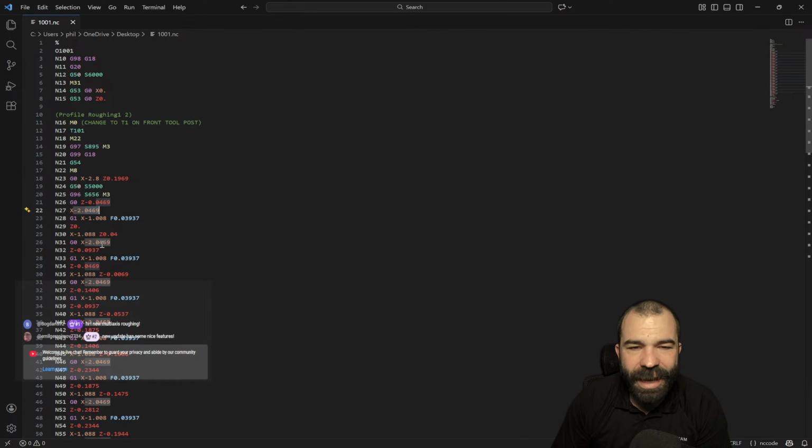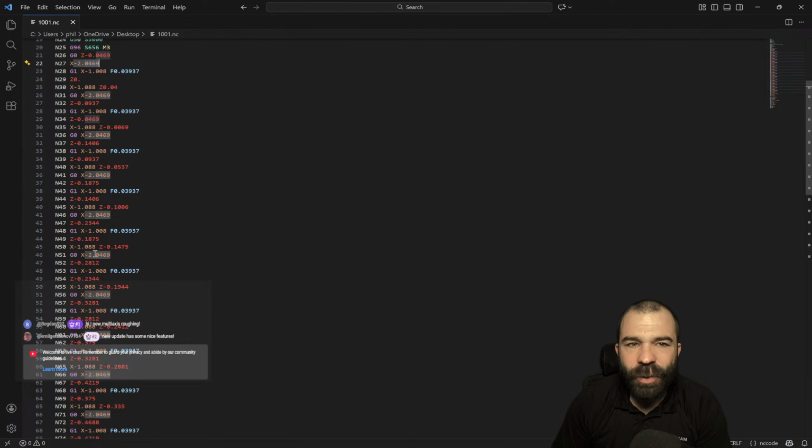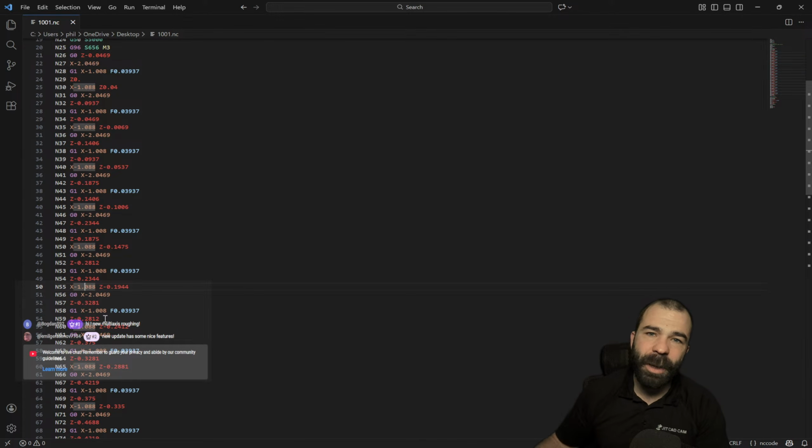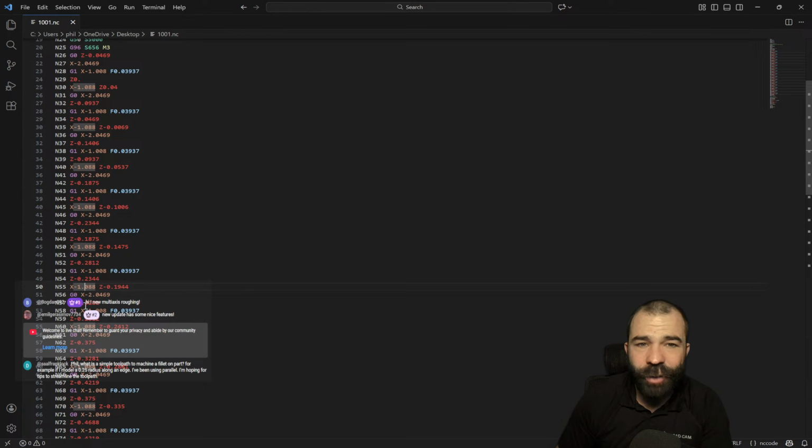We are now on the X negative side when it comes down to feeding to 0. So again, just by going to 101 on the turret, this was the solution to the problem. A lot of people were saying a lot of outlandish stuff. They were saying you should get your post edits made, you need to submit this to ChatGPT, and it had nothing to do with that at the end of the day. All he had to do was change his turret number.